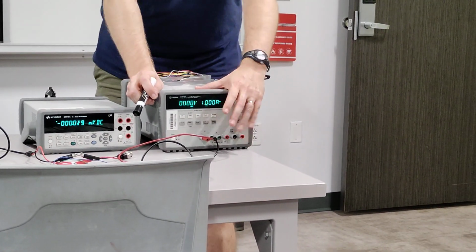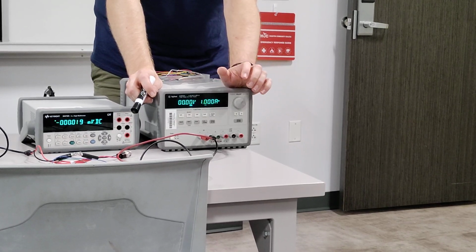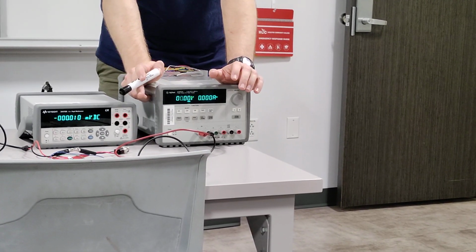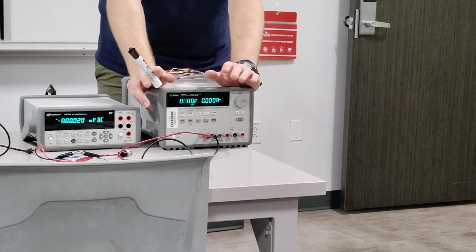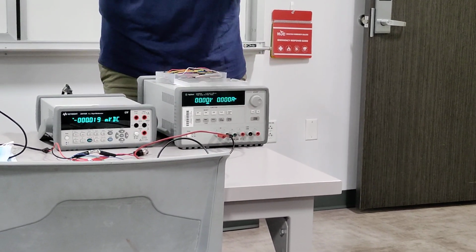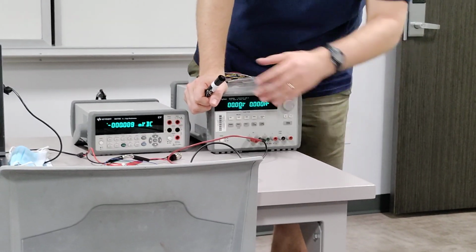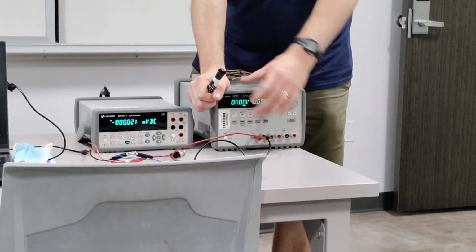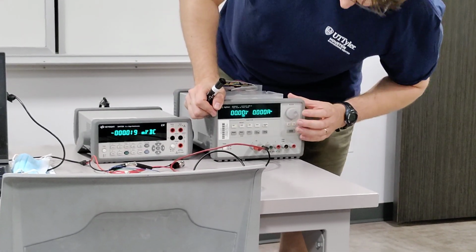When you hit output on, however you have it set up, all 3 of those channels turn on. So when you get to a lab that is not lab 2, and we will obviously talk about it when we're closer, you're going to want a 10 volt supply and a 5 volt supply. So you're going to do a 10 volt supply out of the plus 25 volt channel and a 5 volt supply out of the plus 6. Hit output on, they're both going to turn on.